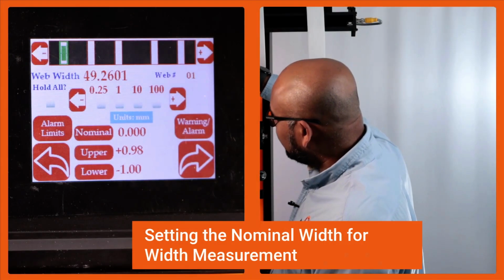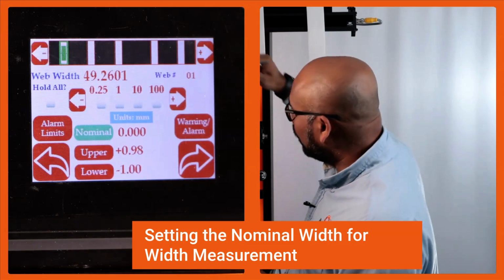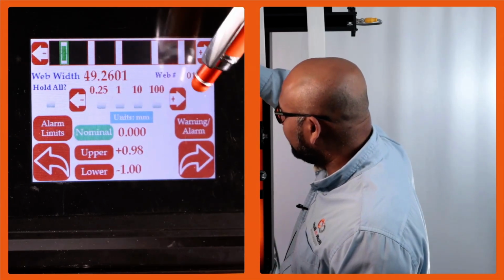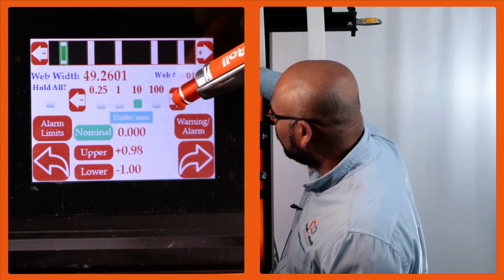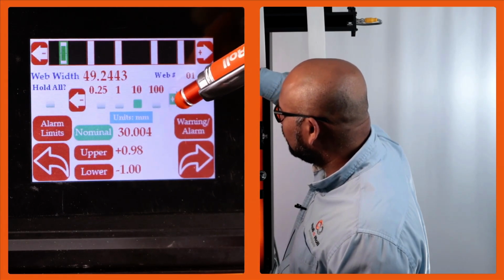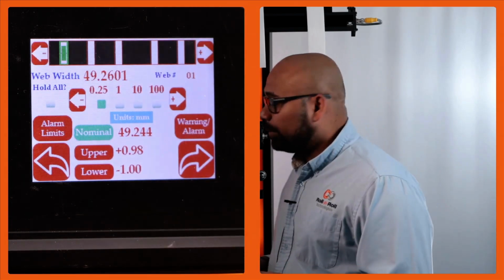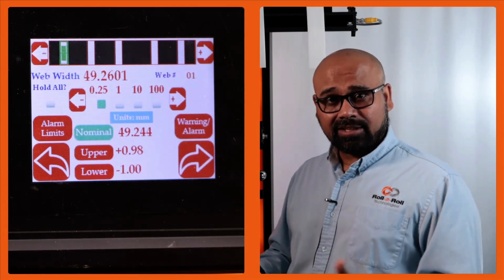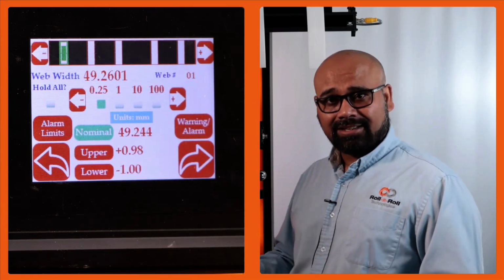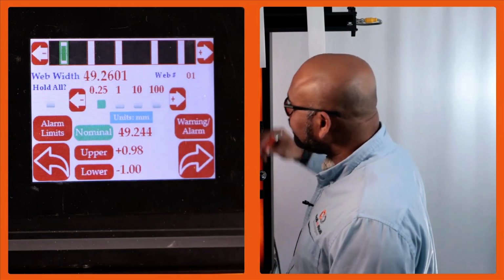In order to set the nominal width, we're going to press that nominal width icon, and then we're going to choose how much increment we want to make. I'm going to do 10 millimeter increments here. So I'm going to change that to 50 millimeters. Okay, so the nominal width is 49.24. That's it. There's no need to save anything here. Anytime you change that parameter, it is automatically saved into the memory. So when you power cycle it, it comes back in.